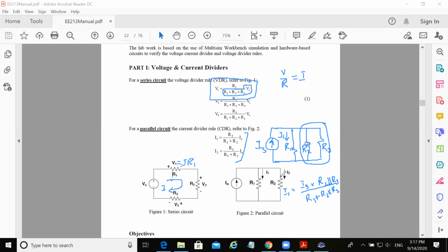Okay, guys, very good. So, in order to summarize, before I move forward to the next page, I would say that when two or more resistors are connected in a back-to-back fashion, which ensures that the same current flows through all of them, we say that they are connected in series. On the other hand, when the two resistors are connected in this fashion where they share their terminals, so this terminal of R1 is shared with this terminal of R2, and similarly the other terminals are shared, they are connected, right? When we have this kind of situation, we say that the resistors are connected in parallel.